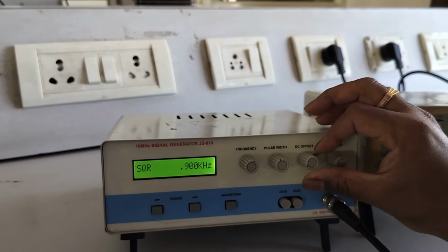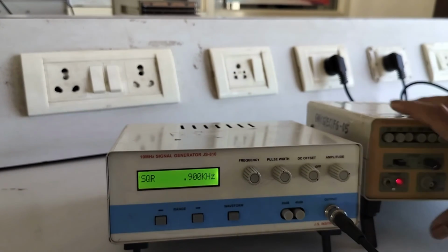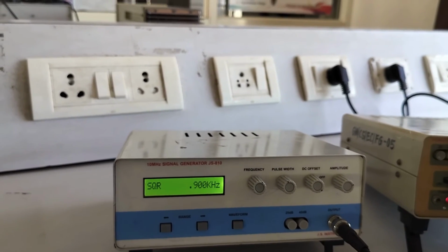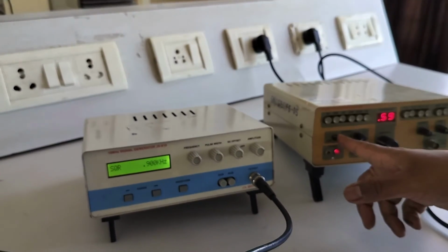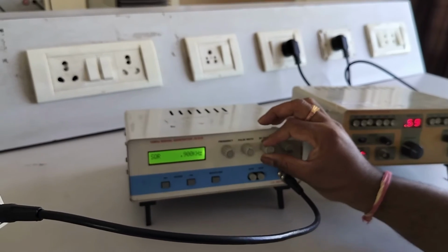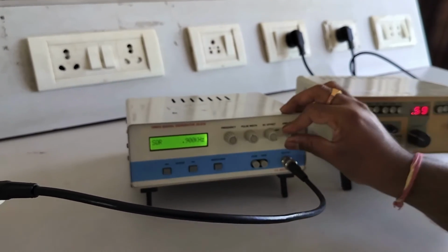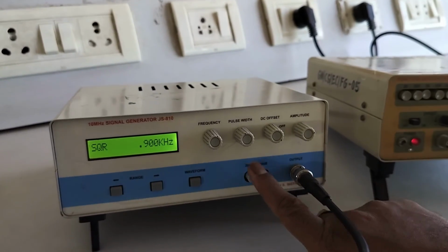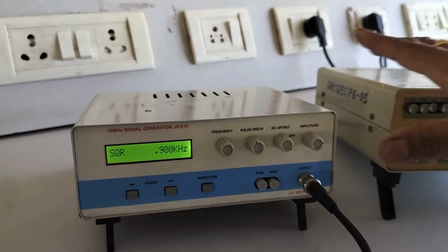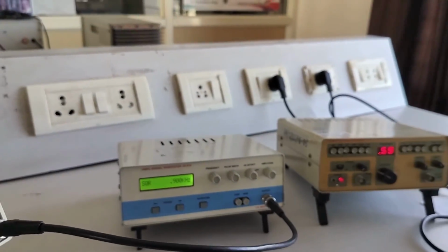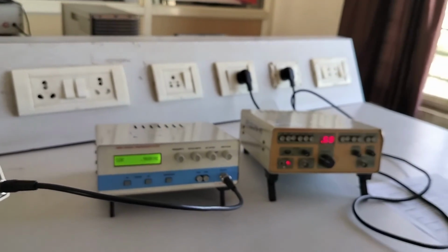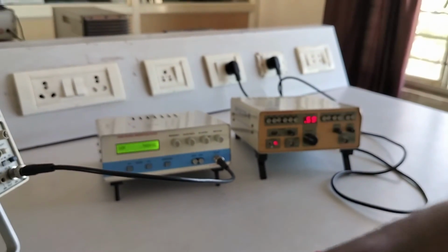It is the offset. Always it should be in the locked position and it should be in the off position. In your electronic applications, if you are not using this, you make it off. This is a very important point. Offset should be in the off position. And it is an amplitude knob as I told, 20 dB, 40 dB. The same function generator has some advanced features, an LCD display. So this is about the function generator. I think I have covered all the points.